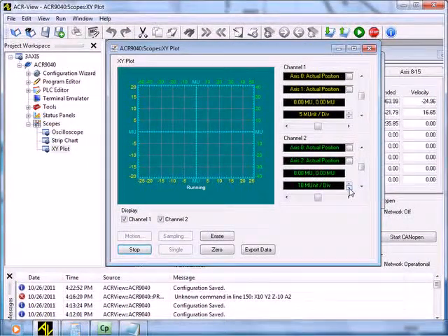Another advanced feature of the ACR9000 is the time-based move. Instead of setting the accel, velocity, and decel and stop ramps for each and every move, if you want to set time for the move to complete, use the tmov. This command automatically calculates the new master profile parameters to do the moves in the specified time. The new parameters, accel, decel, stop, and velocity, are not greater than the user specified value.